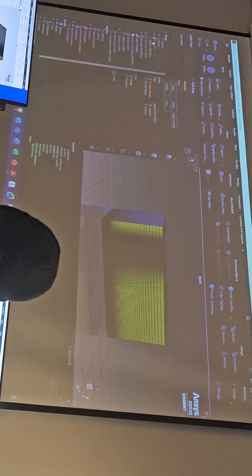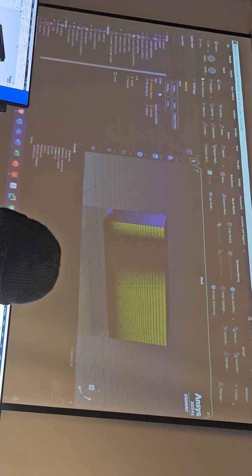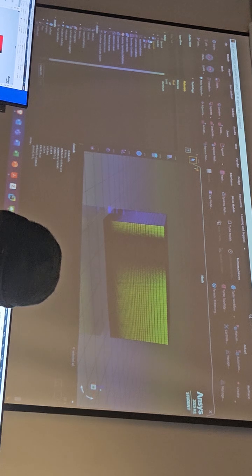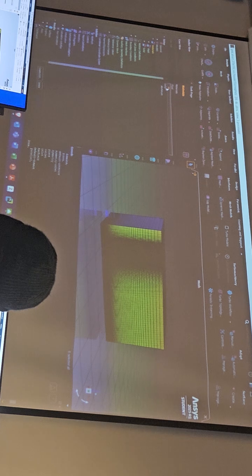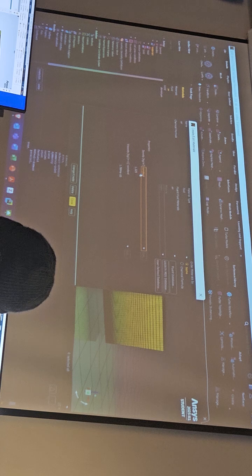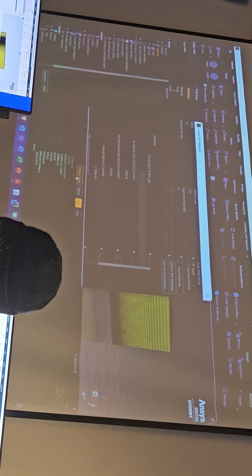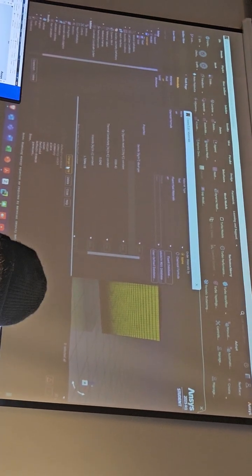So as a first thing, I define the material. So this is a fluid region. There is no solid except for the boundary conditions at the plate. So in materials, I double click on materials, and in fluid, I can change the air model. I change the density from constant to ideal gas. So that depends on pressure and temperature in the domain. Change/Create. In Fluent you always have to hit Change/Create in order to save the settings that you are modifying.